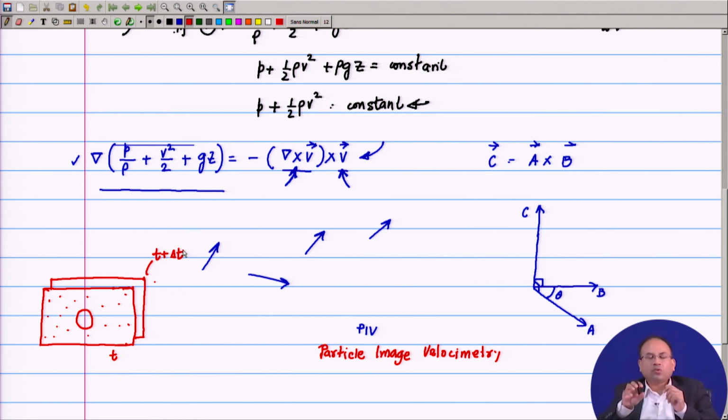If you have, say, a tennis ball like particle, and you have a flow that is bending sharply and twisting, turning, your tennis ball may not really follow the flow faithfully. So, you want particles that are really small, so that they follow the flow faithfully, they can come to equilibrium with the local flow speed quickly, etc.